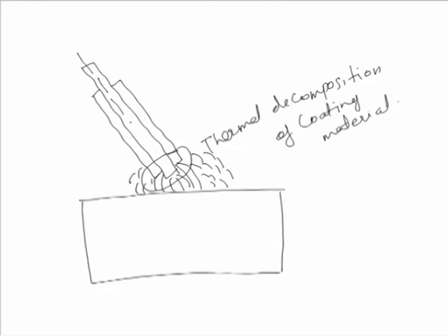At the same time, sometimes if improper welding conditions, like too high a welding current, are used, then because of the high electrical resistive heating of the core wire itself, because of I squared R T heating of the core wire, this coating material itself is damaged by the electrical resistance heating much earlier than when it should decompose to produce these inactive gases.